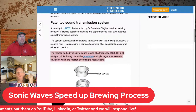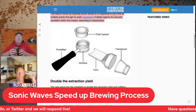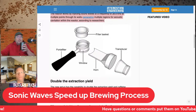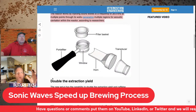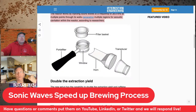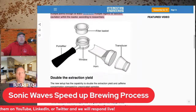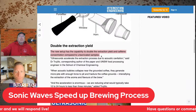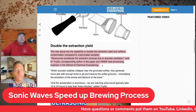Yeah, so I don't think it's going to be too difficult since they modified a Breville espresso machine. The only thing is that the transducer and the horn are going to need to be properly designed and tuned for each portafilter. So there's a couple things. The stainless steel parts have to be able to withstand corrosion from prolonged ultrasonication. There has to be tight coupling to the brewing basket.